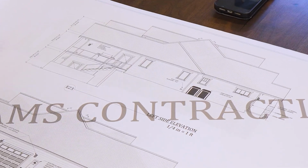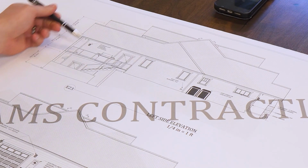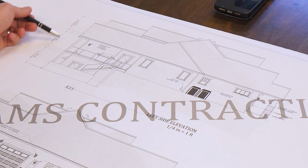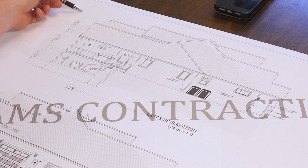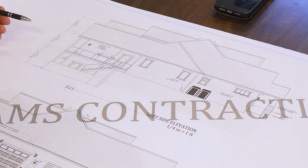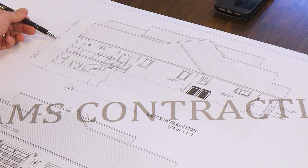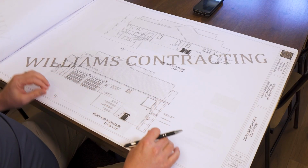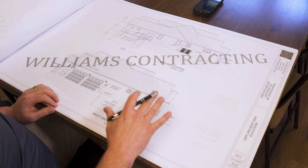I just want to highlight this on sheet 4. We have our wall heights called out for each of the floors. Basement, wall height 9 foot 1 1/8. Main floor, wall height 9 foot 1 1/8. Third floor, 8 foot 1 1/8 wall height. Each of these, 82 BOH, is 82 inches to the bottom of the header. So that dictates our window heights on the exterior of the home. Same thing goes for the main floor. That's 90 inches bottom of header. And in the basement, we had 90 as well. That concludes the main overview of our elevation sheets.